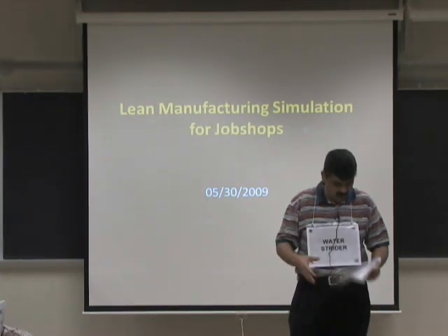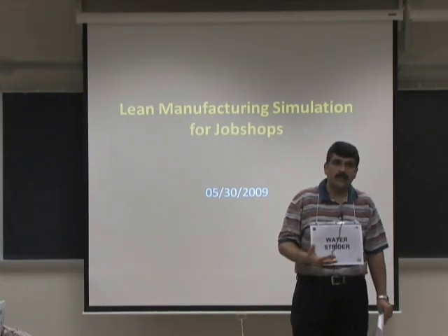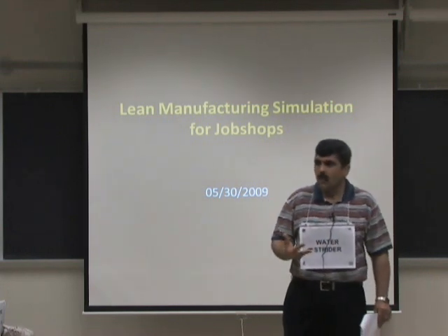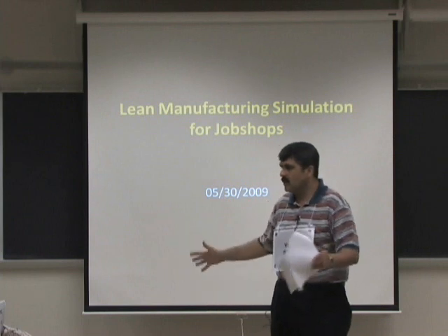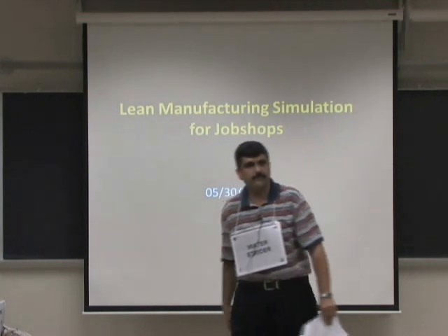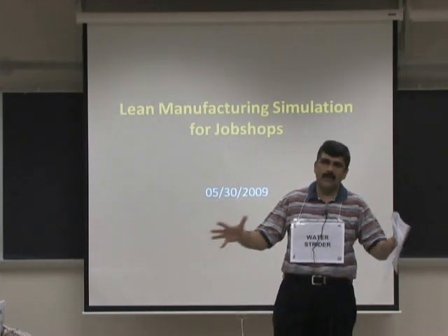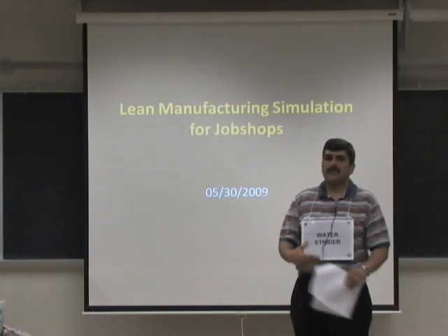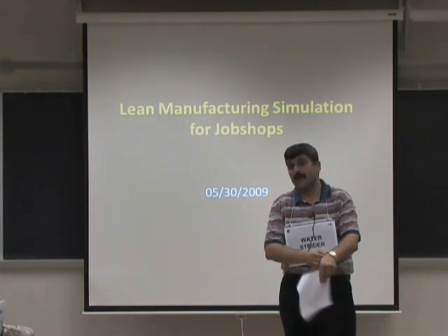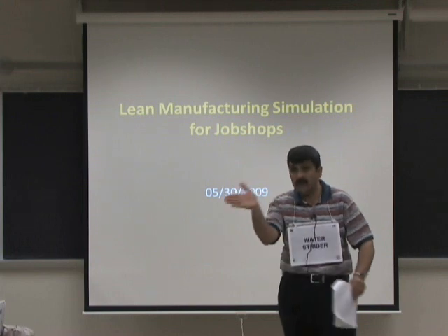Product mix rationalization. The third thing, of course, is facility layout. Now, we've gone to the textbook solutions, right? We've said process layout. What's a process layout? All equipment of the same type will be in one area. Cellular layout, well, you organize the cells into families. But what we forget is that there is a spectrum of potential layouts in between those.